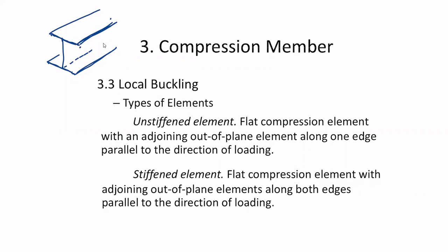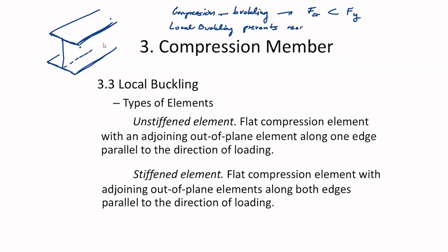So I can summarize here that compression buckling will prevent you from reaching Fy. And then local buckling prevents, what? Prevents the reaching of F critical. So it's getting even lower.